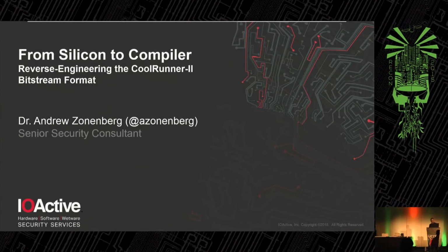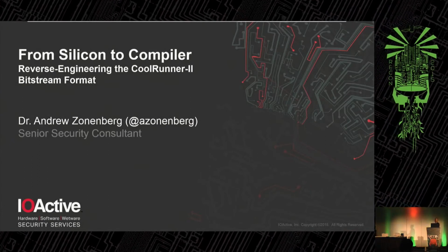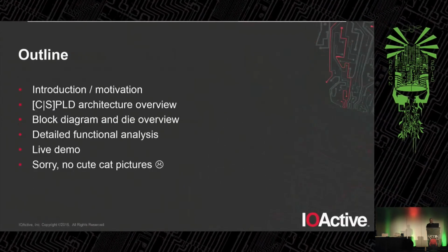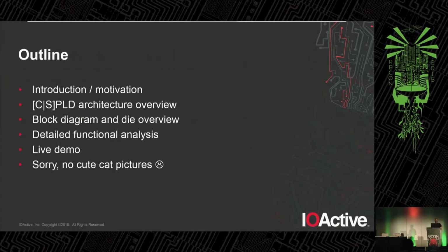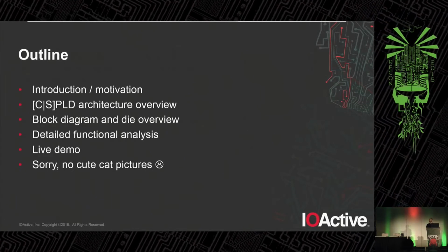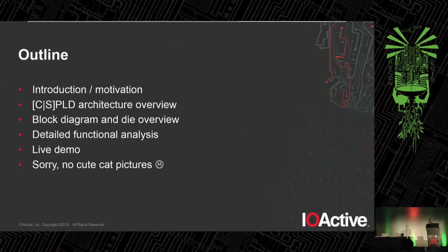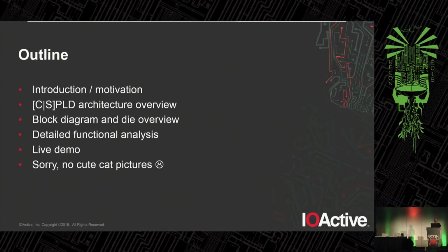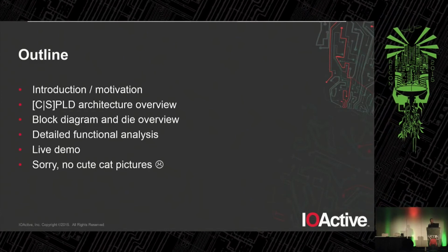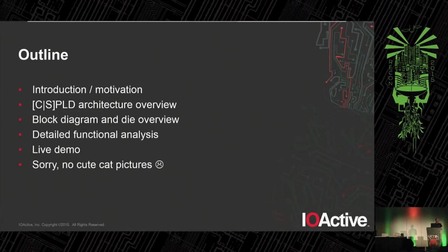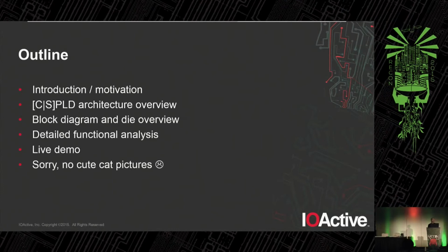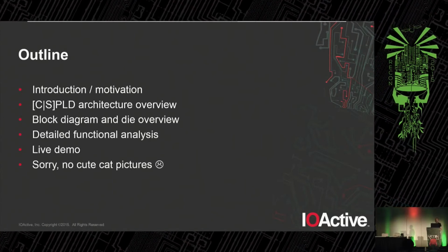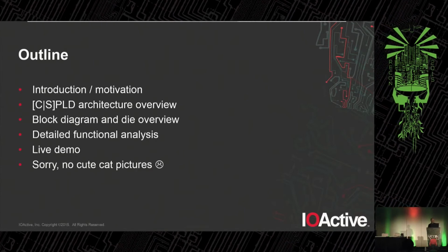Okay, sounds good. So my talk is called From Silicon to Compiler, and it's pretty much that. We're going to start off with what we're doing and why we're doing this, then a little bit of architectural background on programmable logic for those of you who have not done work on programmable logic before. Then jump to a block diagram of the device. We'll start with a high-level overview of the silicon, and then we'll drill down into more interesting stuff, down to transistor level and gate level circuit analysis. At the end, I do have a live demo of firmware produced by my tools running on live silicon.